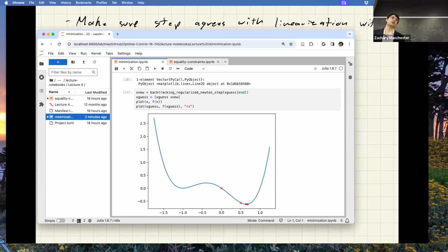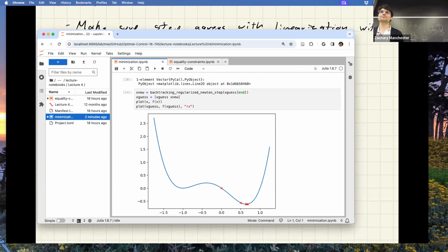You always do these things. On a non-convex, nonlinear problem, this won't work without those two extra tricks. You need regularization and backtracking always. You always have to do it. Otherwise, it won't work. That's why we're talking about it. This is not just for kicks. It's actually important stuff. The other stuff about weird deadbeat control, that's all for fun. This is actually important.